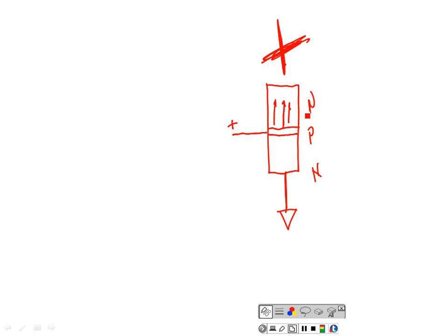In fact, to forward bias this junction right here, if it's silicon, it's going to take about 7/10 of a volt. As soon as I get 7/10 of a volt, that junction is forward biased. As soon as it's forward biased, we have all these electrons over here. They're going to come up here and start flying toward that. And you've got this little tiny base that doesn't have hardly any majority carriers in there, and it hits this little old tiny base, right?